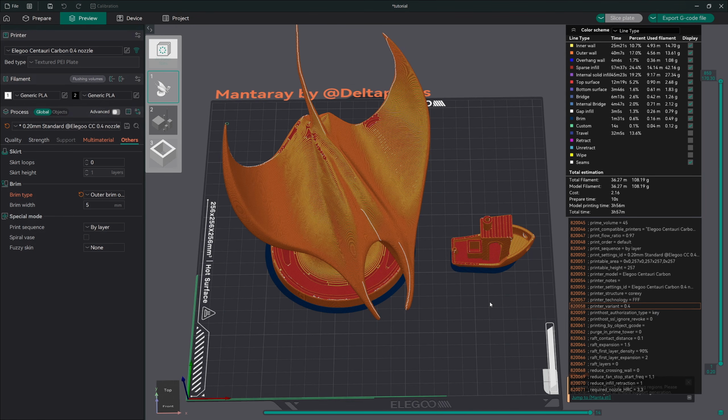When I first started 3D printing, I used a brim on almost everything just as an extra piece of mind. And honestly, it was well worth it. Especially if you're like me and you tend to start long prints before heading to bed, using a brim can be the difference between waking up to a successful print or a complete failure. For me, that extra bit of bed adhesion is always worth it.